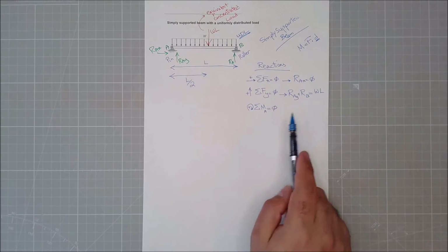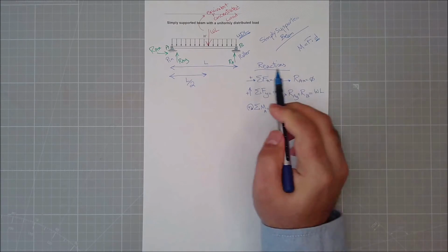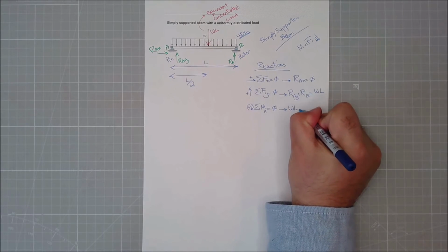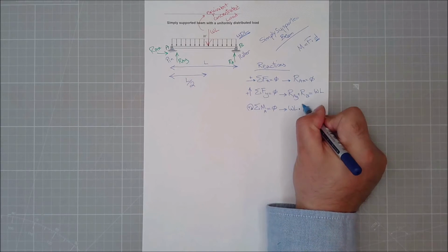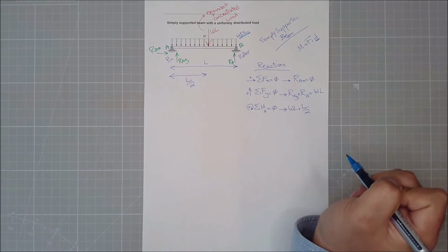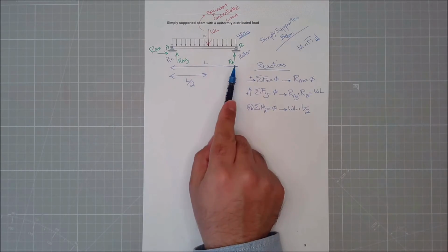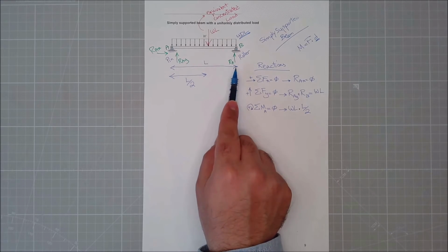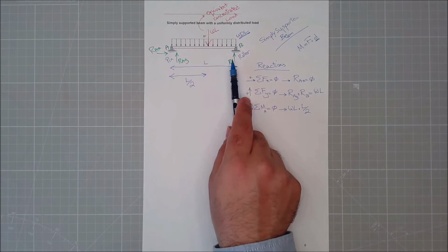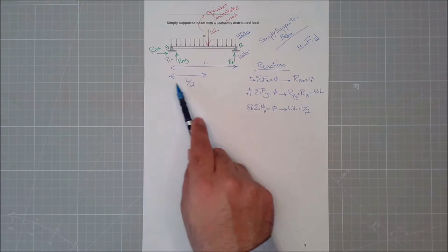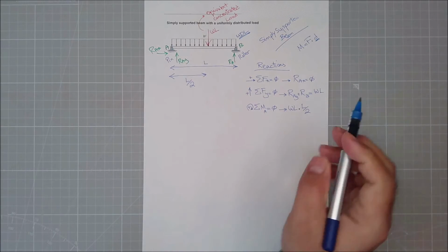Isn't that the same direction that I have considered positive here? Yes. So it will be that force, which will be WL, times the distance from here to this point, which will be L divided by 2. And it's positive because it's in the clockwise direction. But look at RB. RB has a perpendicular distance all the way to point A. And if I follow the arrow of RB along point A, as you can see, it is counterclockwise. So it will be negative.